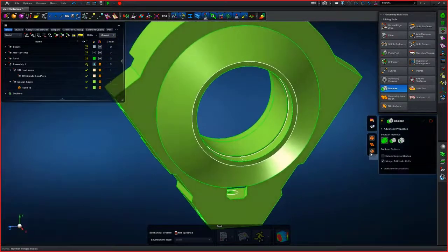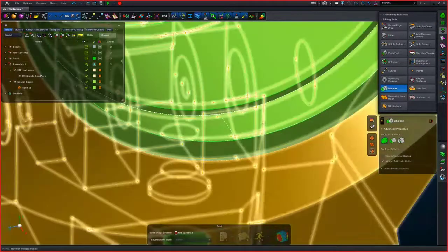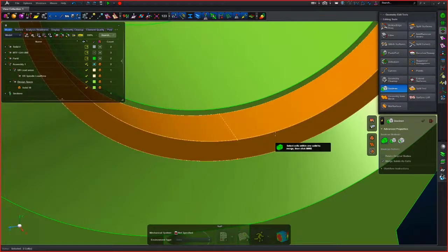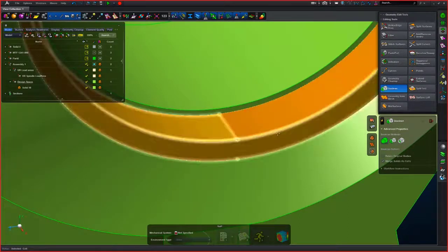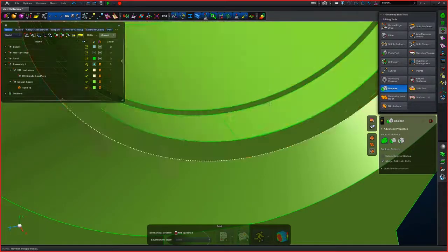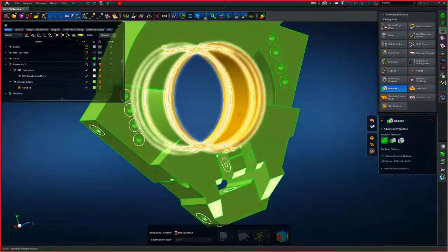Now, in this particular case, I just want to draw your attention to one additional defect, and that was some small sliver cells that remain. That means these two faces of those solid bodies weren't perfectly modeled in the CAD system, and we can either replace the one face with the other, or if you wish, simply Boolean those cells again if you're a bit lazy, like I am most of the time.